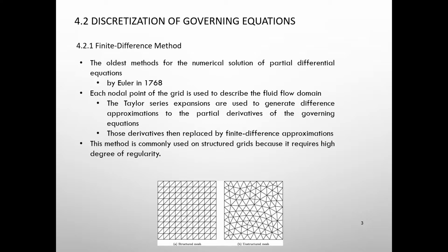It depends. If your case involves some temperature, you need to calculate how temperature is convected into the fluid. You need to include energy equations, but most of the time the most basic equations are the continuity equations and momentum equations, though that also depends on your problems.